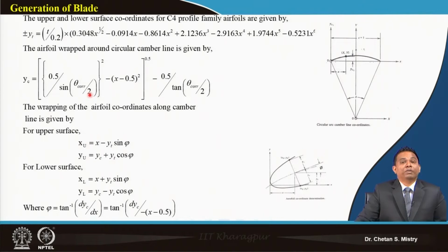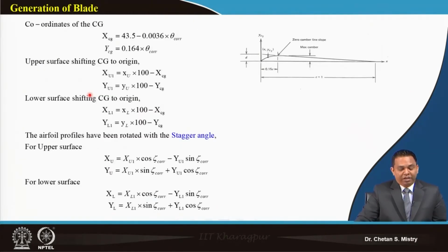Okay. Do not miss this part. Purposefully this slide has been kept intentionally here. Now, in the same way, the stagger angle we considered for our earlier program, that input will now be corrected. The stagger angle is corrected, so accordingly we will get our blade geometry.